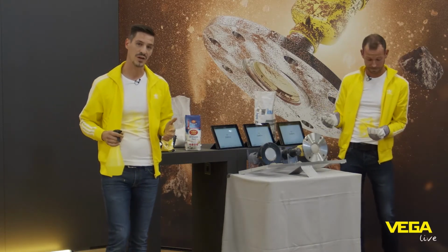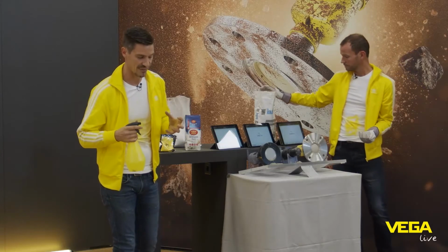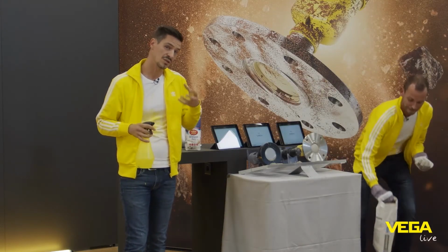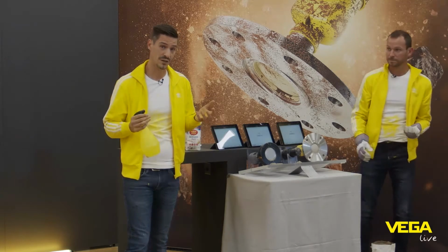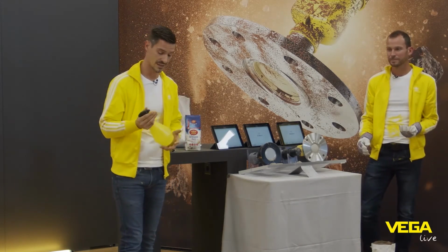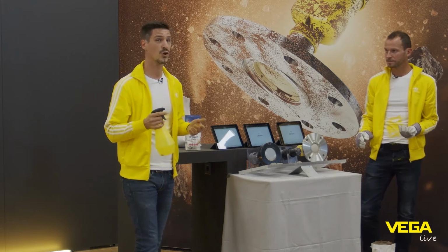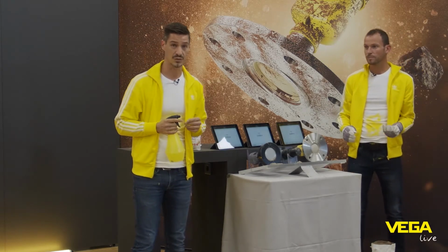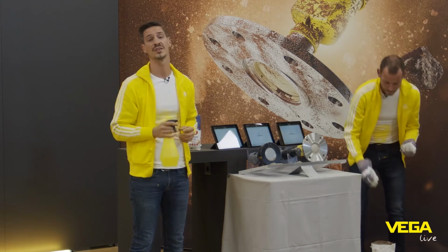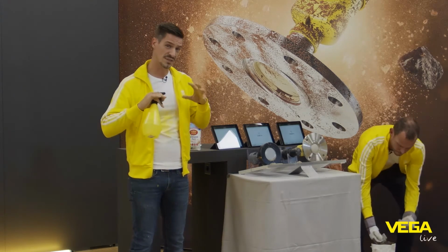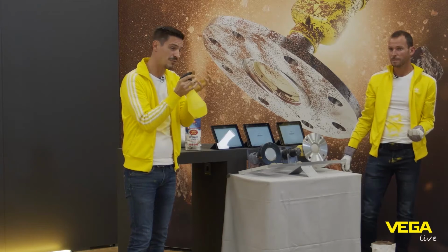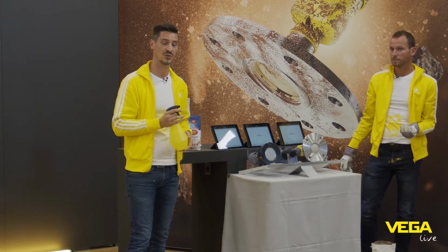In real life, we have real sticky, heavy, strong build-ups. And this will be created not only with dust. There's a second factor, it's liquid, it's water or condensate. Condensate is generated normally at the coolest point within a silo, and this is normally our sensor. So humidity will start to generate condensate there. In combination with the dust atmosphere, we will see that heavy, sticky build-ups will be generated.